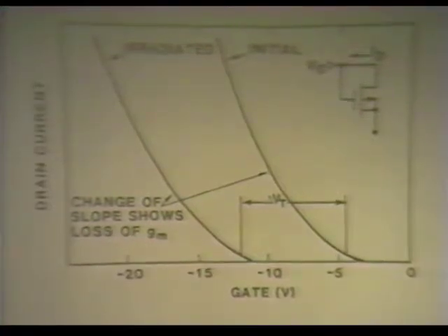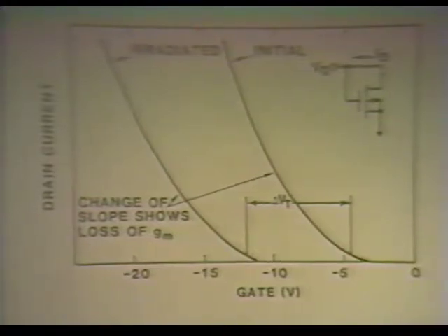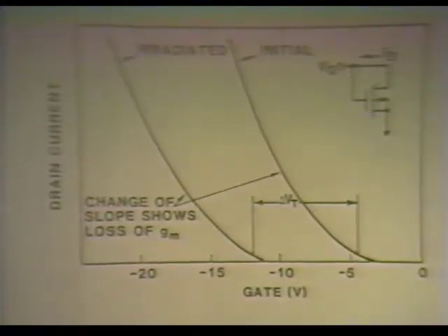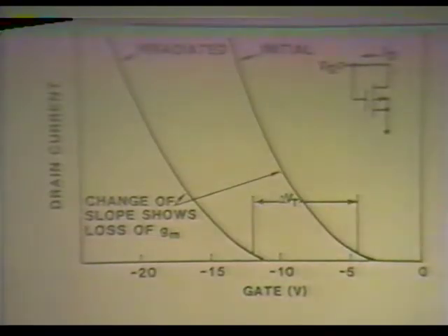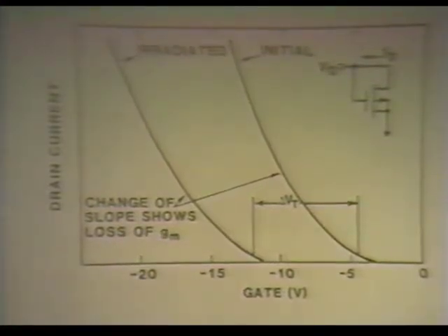So basically what you've got then for the two major types of radiation that we worry about at Sandia is neutrons affecting the bipolars by creating defects in the silicon, thereby creating lots of traps for your charge carriers. As they fight their way across the base, they fall into these traps, and it decreases the efficiency of your transistor.